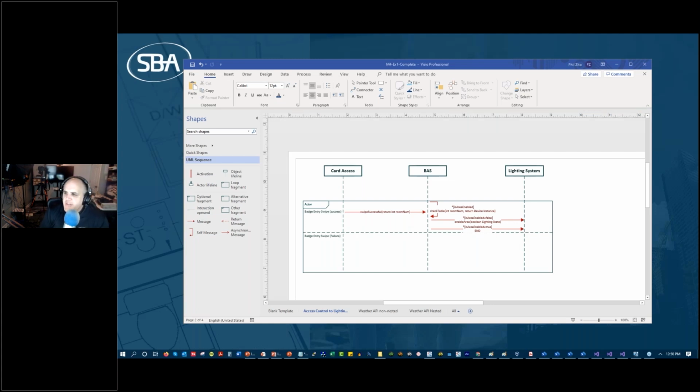Okay, so I just went through this conversation with one of our students the other day. They're looking at using a PLC system at one of their facilities in lieu of a DDC, and they've got DDC in the rest of their buildings. PLC is programmable logic controller, DDC is direct digital control, for those of you who don't know. PLC is more akin to a building automation architecture, whereas DDC tends to focus on the field controllers, and BAS is actually the whole system.